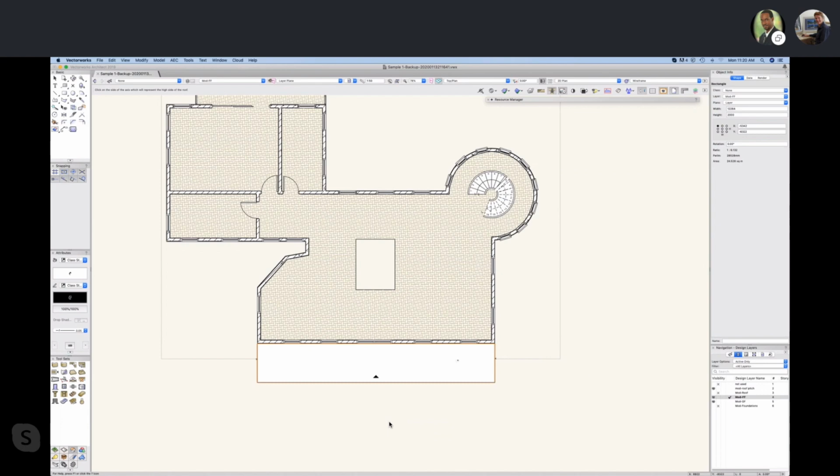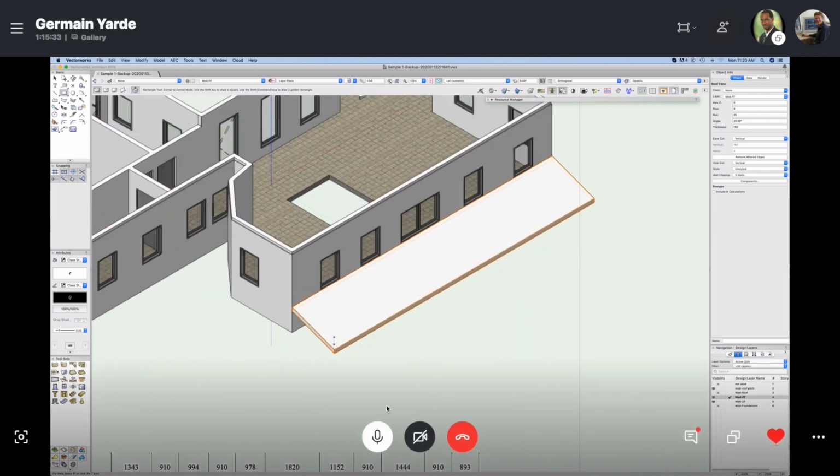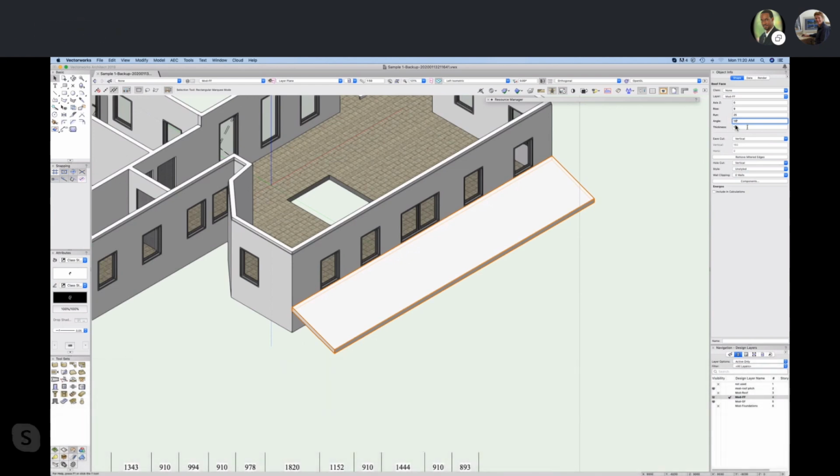Okay. So click. Now, it won't look any different in plan, but look in 3D now. It's pretty cool. Okay. So what can we do with this roof? We can change the angle easily. So if you change the angle a bit less, go below those sills, like 18 degrees. Yeah, that's cool. You see it will just drop down nicely, so that's pretty cool.